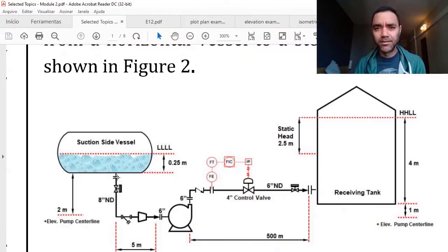So if you are in an industrial facility, in a production process that already exists, get the documentation, but always go to the field to verify that everything matches one with another. Okay, the same goes for the piping and instrumentation diagram. And here it's a matter of experience.